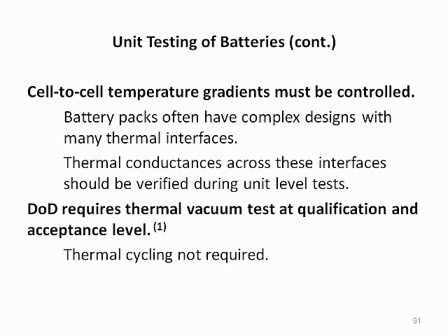Batteries usually have requirements to limit cell-to-cell temperature differences within the battery. Meeting such requirements can be challenging because battery packs often have complex designs with many thermal interfaces. Thermal conductances across these interfaces should be verified during battery-level tests under realistic environments. DoD explicitly requires thermal vacuum testing for batteries at qualification and acceptance levels, but thermal cycling is not required.